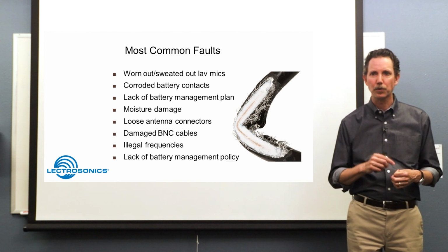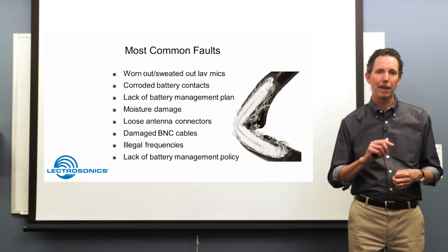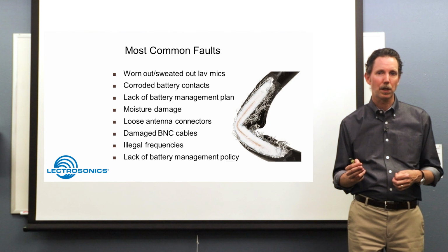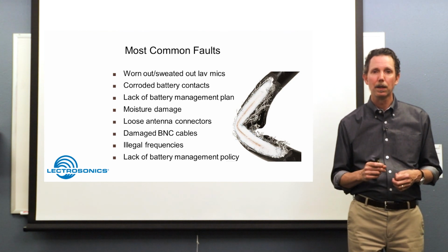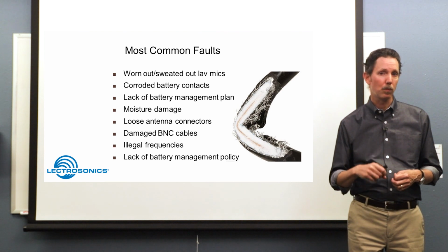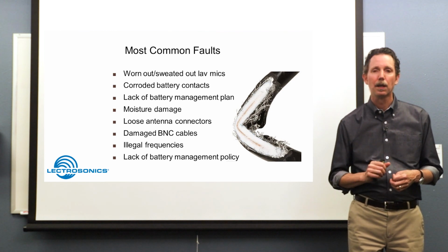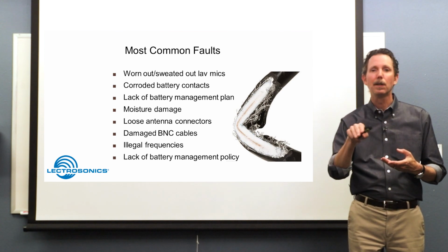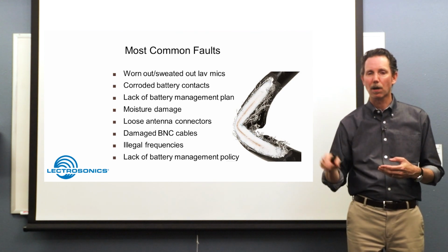Mark every battery with first charge, first use date, and then replace them on a schedule. I typically like to replace rechargeable batteries if they're lithium ion, once a year is appropriate. If they're nickel metal hydride, I would replace them twice a year, because how much charge they can hold definitely diminishes with every charge.